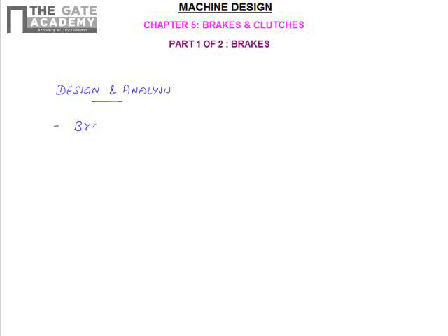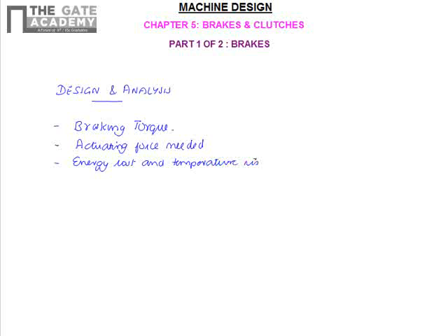One is braking torque, then we have actuating force, that is how much actuating force is needed to bring the body to rest. Then what is the energy lost? And we have seen this energy loss is converted into heat, so therefore what will be the temperature rise of the rotating body? So these are the parameters of interest in design and analysis of brakes.